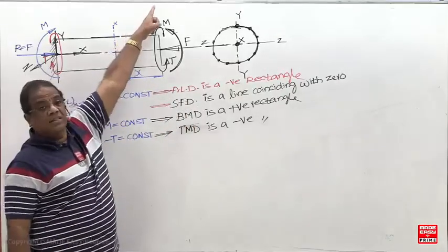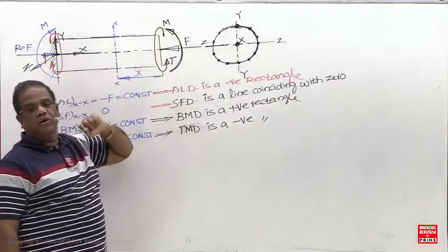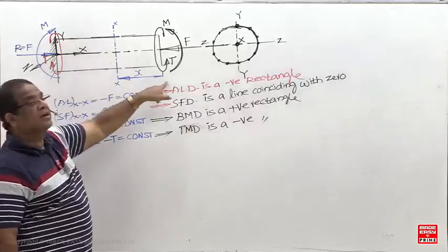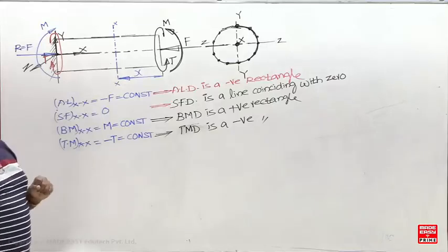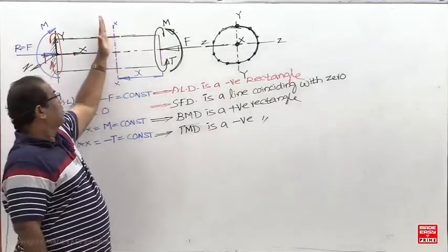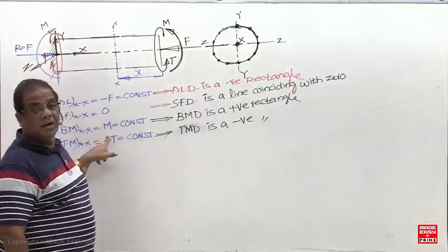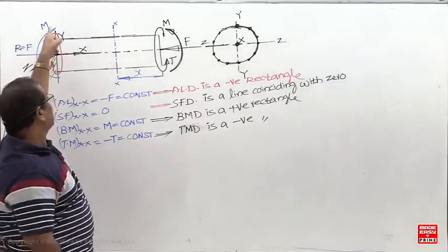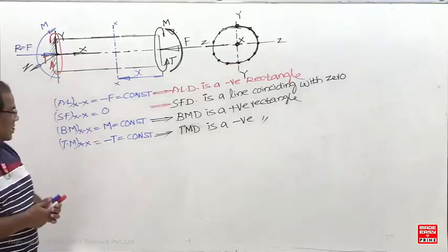But by chance, if a constant point load is given in place of this M now, then what are you going to get? Shear force equal to plus W. And what is the bending moment? Minus WX. Means bending moment is varying. So where is the bending moment maximum here now? In that case every cross section is not critical, but here every cross section is critical.